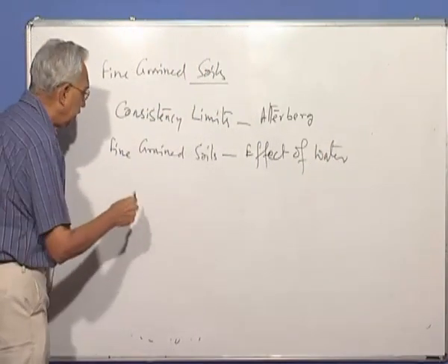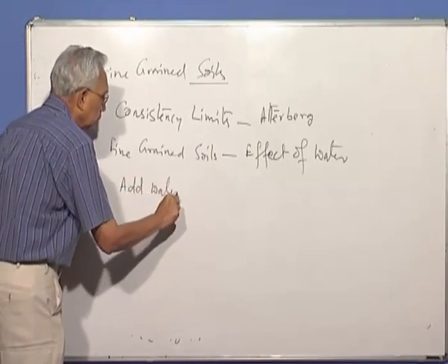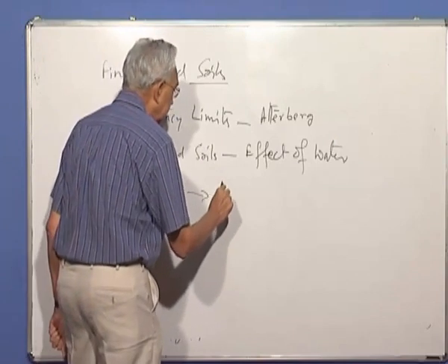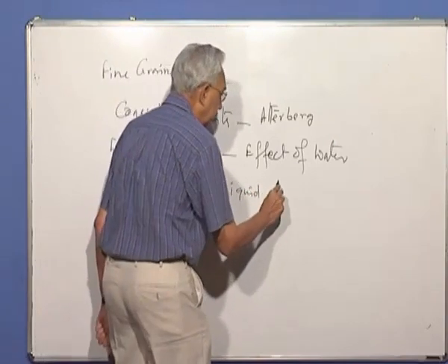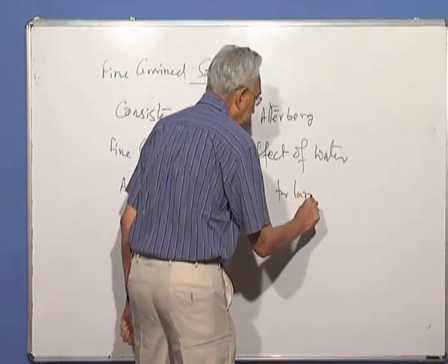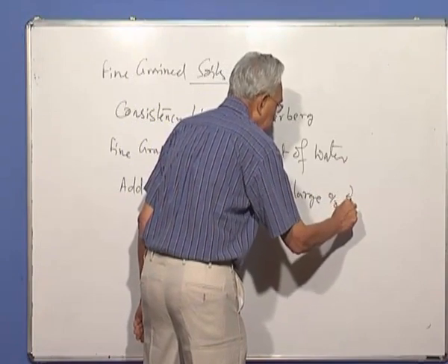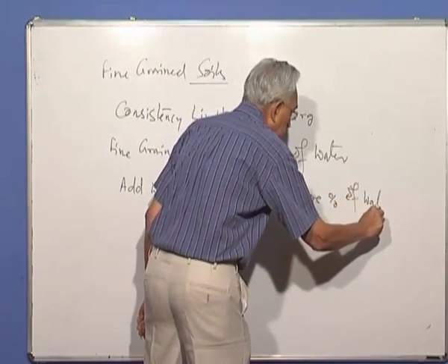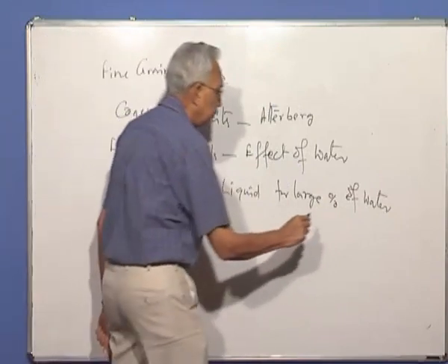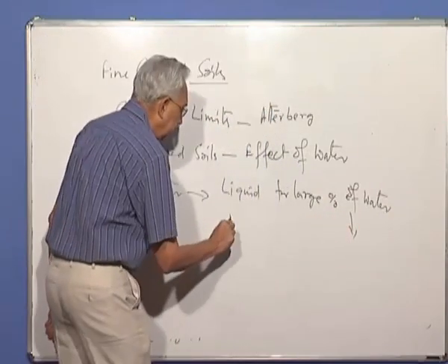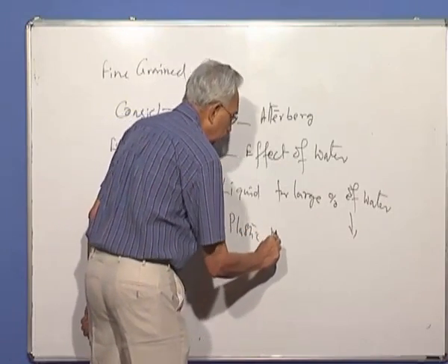If you add water, the fine-grained soils behave like a liquid for a large percentage of water. If I start decreasing the amount of water, it behaves like a plastic material.